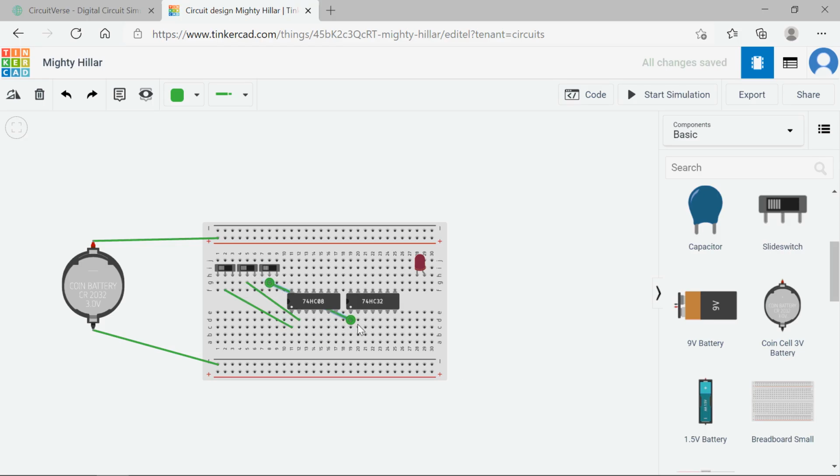Okay, so this wire here is input C, the input of our OR gate, and I've done that here. I ran this wire across here. Now the output of our AND gate is the other input of the OR gate. And see how it doesn't matter? I don't have to put it right up there. I can put it anywhere in this column because on these breadboards, everything in a column is connected. Finally, the output of my OR gate is the output.